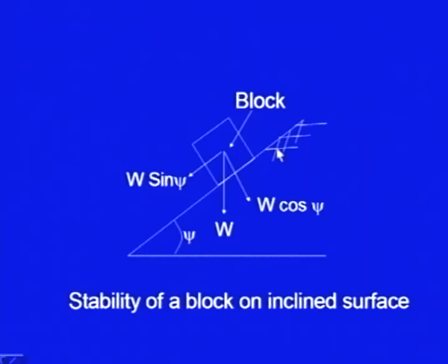So, this is the basic thing which we are going to use in stability analysis. We are going to compute the mobilized value of the shearing resistance and the limiting value of the shearing resistance, and based on that we will find out the margin of safety.